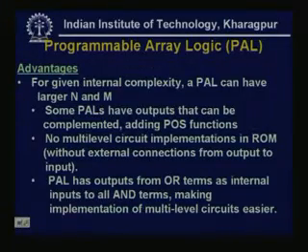Now, what are the advantages? For a given internal complexity, a PAL can have larger N and M, because it has a programmable AND and a fixed OR. So, it can handle larger input variables.